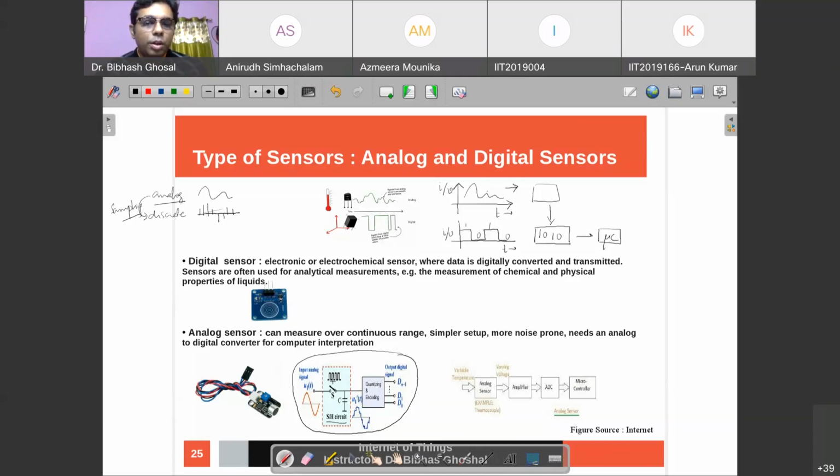So here we have a circuit called sample and hold. It's like a gate that allows the value to be passed for some time. So the sample value would be something like, maybe here you take this as a sample. Then from here onwards, you take this as a sample. You can take from here, let's say, this as a sample. So this is how you can generate samples, and then you can generate this discrete signal.